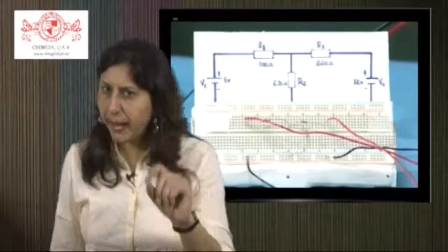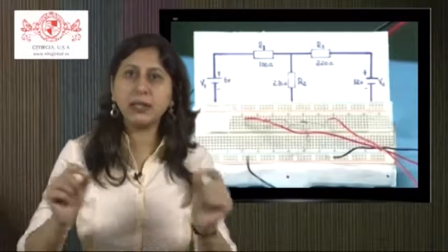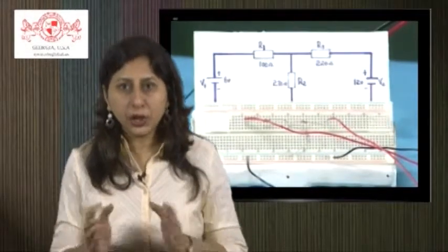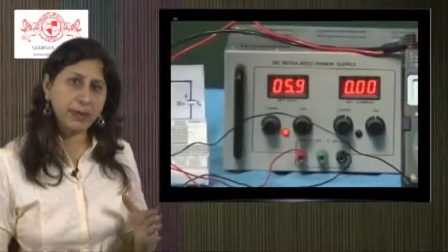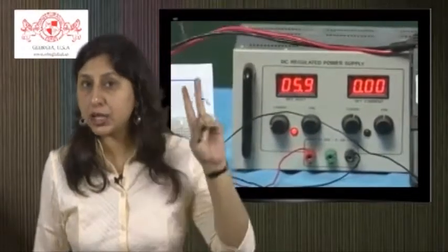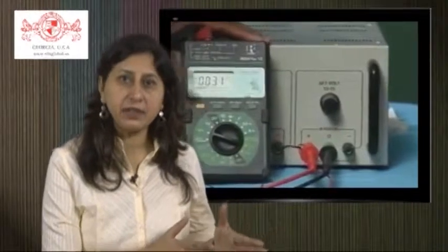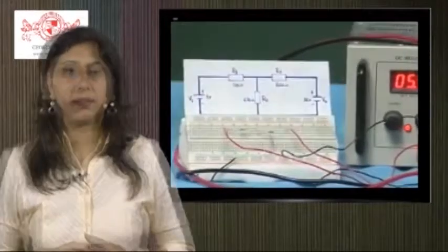Capacitors. A capacitor is a passive two-terminal electrical component used to store energy in an electric field. The forms of practical capacitors vary widely, but all contain at least two electrical conductors separated by a dielectric insulator. One plate of the capacitor contains negative and the other positive charges. Electrons enter through the negative plate of the capacitor and they repel the electrons on the other side.